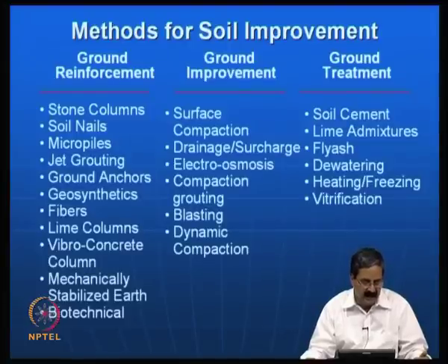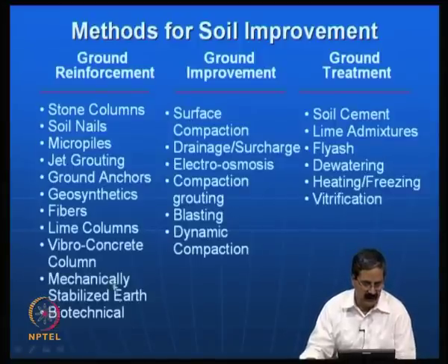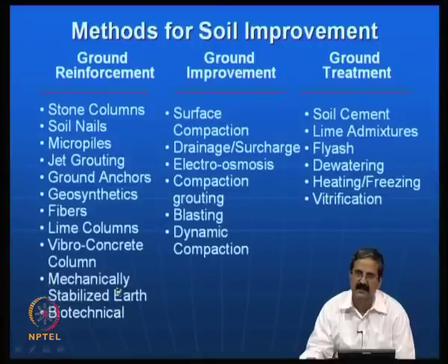Then mechanically stabilized earth, or reinforced earth wall. This is a standard technique nowadays; all the flyovers are constructed with this reinforced earth technique, which is called mechanically stabilized earth. Mechanically means you are using reinforcement there, because of the mechanics of interaction of the soil and the reinforcement, the stabilization of the earth takes place. So, by introducing the reinforcement, we have reinforced earth walls rather than gravity walls or other types of walls like counterfort walls.